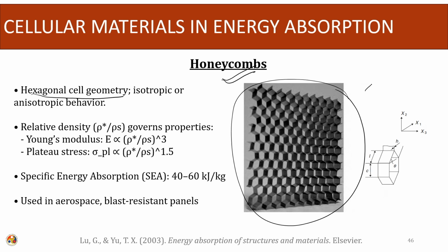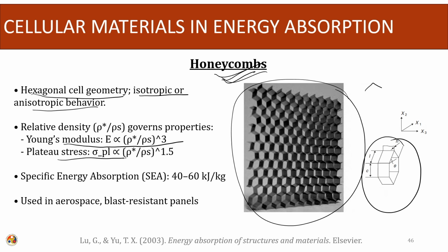So, there are different cells like this, arranged in a regular pattern. And due to this arrangement of the cells, the name honeycomb comes. The behavior can be isotropic or anisotropic. The relative density governs the entire properties. So, the Young modulus is directly related to the relative density, and the plateau stress, the maximum stress, is also related to the relative density, and it is given by this power law.